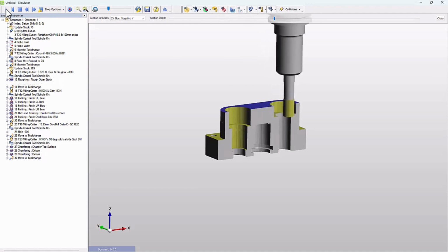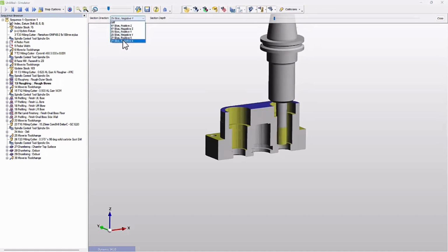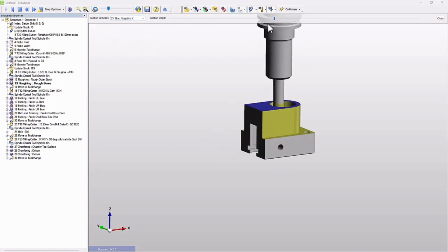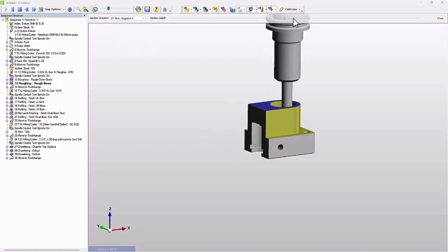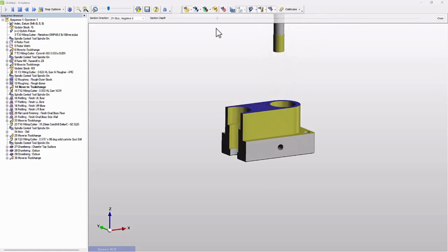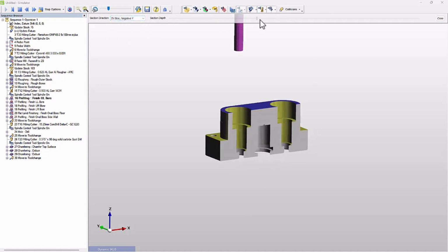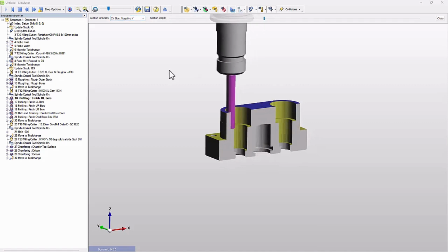Again, we can see the previously machined stock where there is a hole. The roughing cycle intelligently enters through the hole and just removes remaining material to the part per the designation. If we switch the work plane, we can again move the slider and see the level of view sectioned from a different plane if we wish. So the section view, neat tip, hope that helps you out.